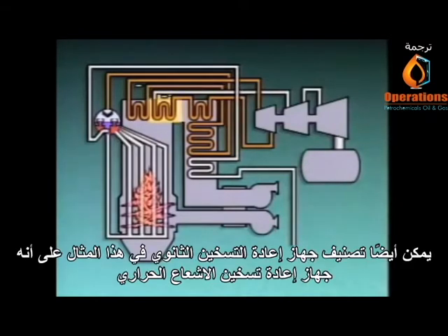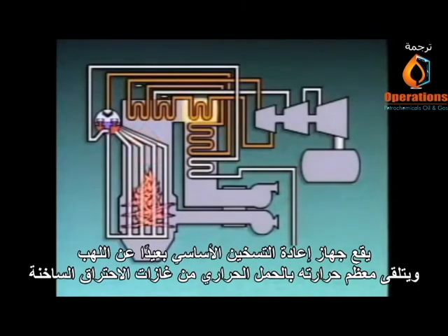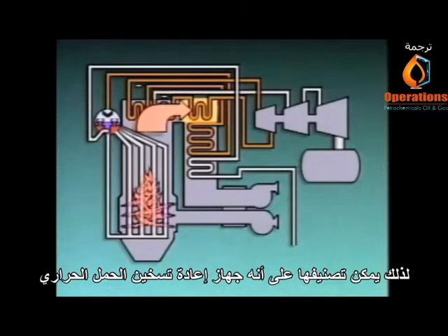The secondary reheater in this example can also be classified as a radiant reheater because it's located in a line of sight with the boiler flames and receives most of its heat by radiation from the flames. The primary reheater is located farther from the flame, and it receives most of its heat by convection from the hot combustion gases, so it can be classified as a convection reheater.